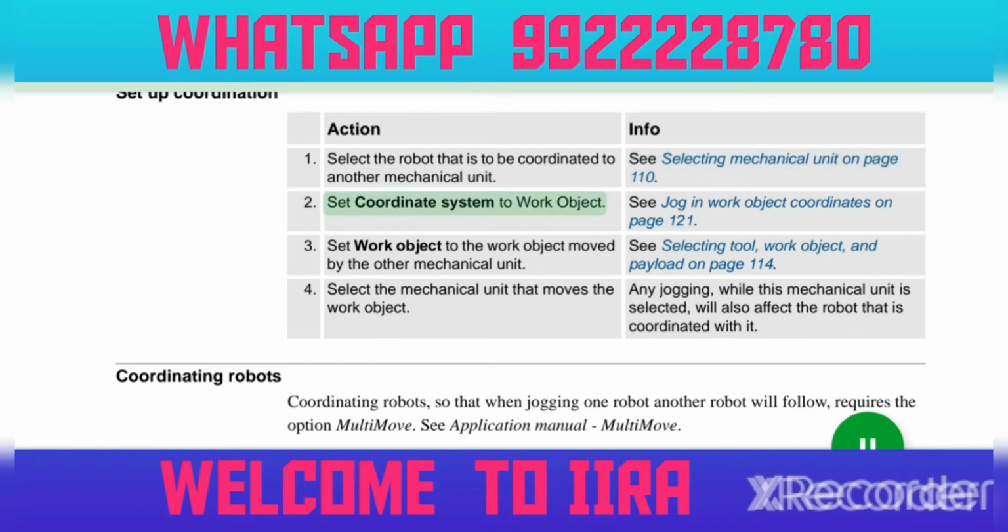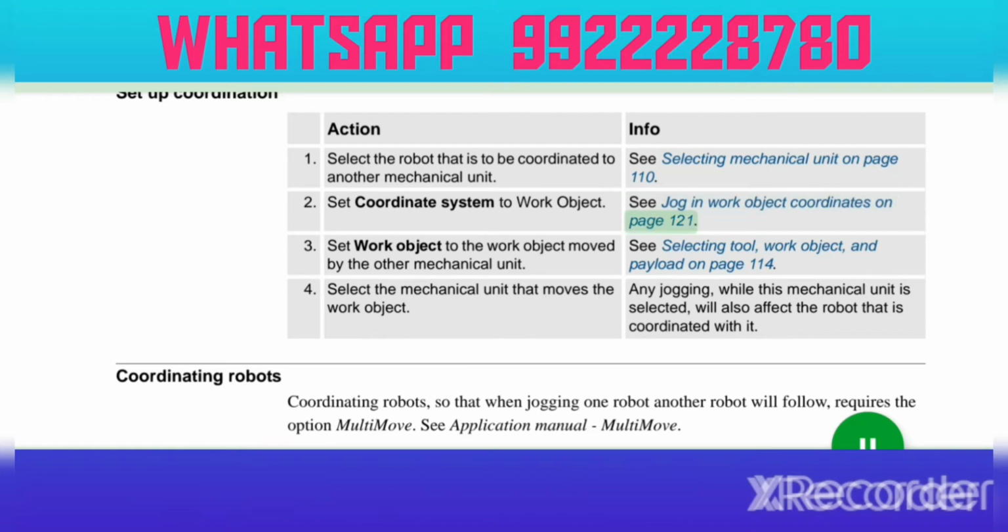2. Set coordinate system to work object. See jog and work object coordinates on page 121. 3. Set work object to the work object moved by the other mechanical unit. See selecting tool, work object, and payload on page 114. 4. Select the mechanical unit that moves the work object. Any jogging, while this mechanical unit is selected, will also affect the robot that is coordinated with it.